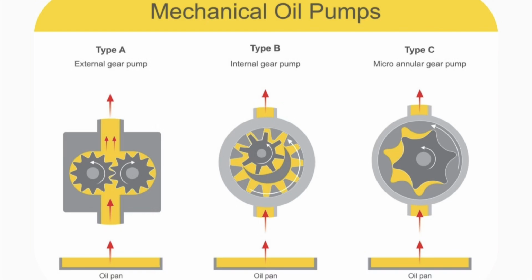1. Gear pumps, simple and low cost. Gear pumps are fixed displacement pumps, moving a set volume of fluid per revolution, known for their simple design, durability and low cost. External gear pumps use two intermeshing external gears. As teeth unmesh at the inlet, oil is trapped between gear teeth and the housing, swept around the outside casing and forced out as teeth mesh again at the outlet.